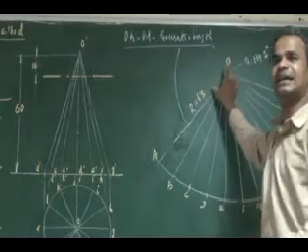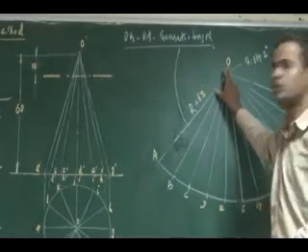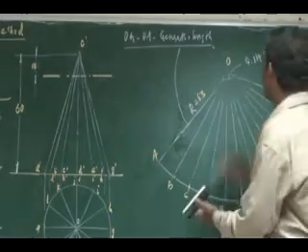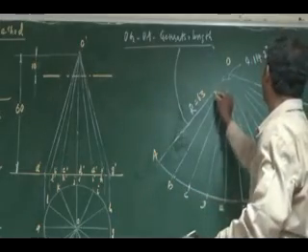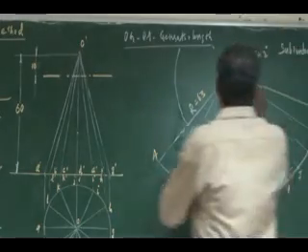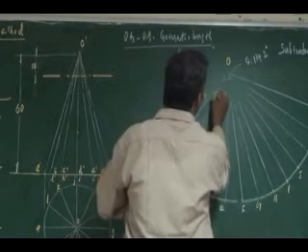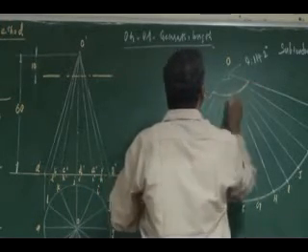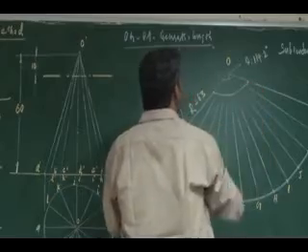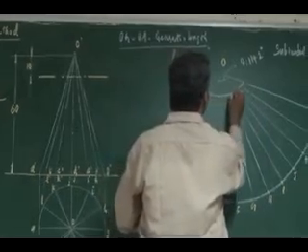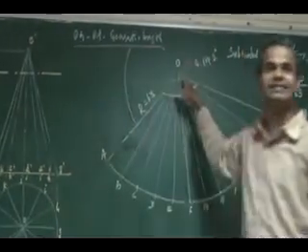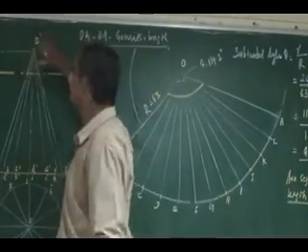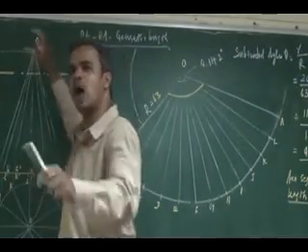Using that center, you draw an arc. You need not show the cutting points here. Since the first cutting plane cuts parallel to its base, the top portion is something like a smaller cone.